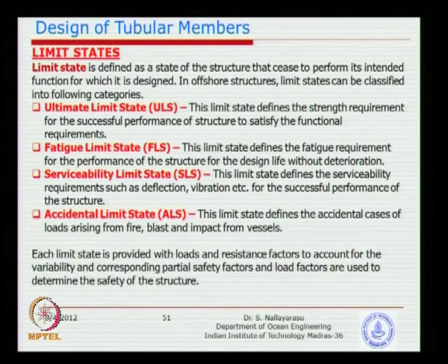For example, you design a structure to support a compressor or a power generating machine. If the vibration is too much, probably the machine will fail. The structure may not fail, but the function for which it was designed is unable to operate, and you will end up switching off the machines. So serviceability is more of a concern in this kind of structure. Then the last one is the accidental limit state, typically designed for accidental cases like fire, blast, and ship impact. These effects we will look at in the last module, where we design for accidental loads.